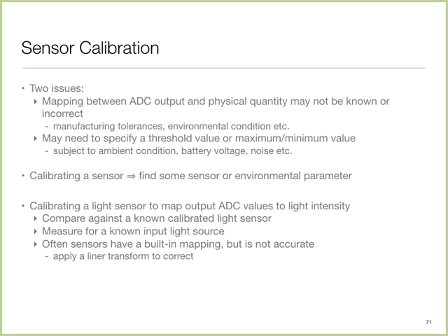Okay, so one is you can do a calibration procedure. The other is you can take a large ensemble of those sensors and train your model over readings from those. So don't just train on one or a small number of instances, but buy multiple batches on different dates, so that you have a diversity of manufactured pieces, and then train the model with data from those. Otherwise, your model may not generalize because the devices may have differences.